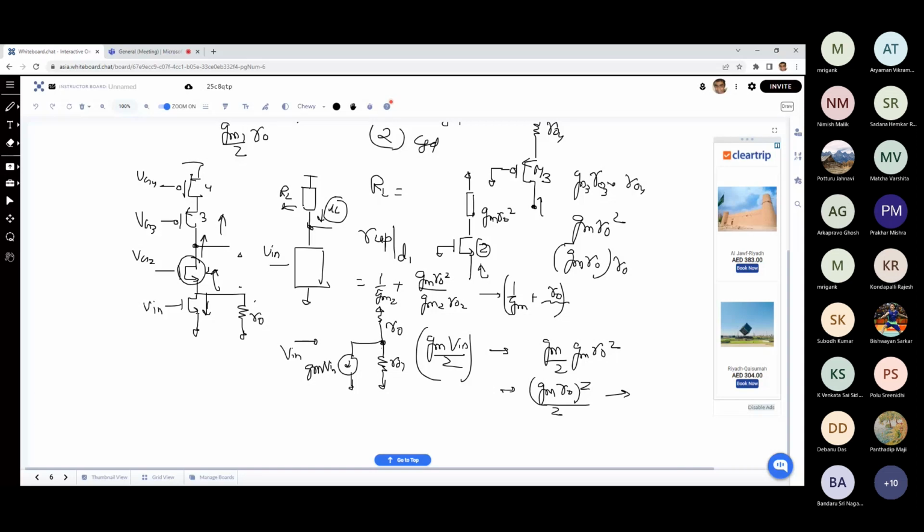In the exact analysis, we have the small signal current getting reduced because of the larger impedance. It is not basically reduced, it is getting divided because of a large impedance looking into the drain. So now you're getting a larger voltage change. Earlier, because the impedance at this node was low, the voltage change here was low. But now this node itself is going to have significant voltage change. This node has much larger change, but this node also now has some voltage change, and the impedance is large, because of which the current gets divided. So we need to account for the actual load.